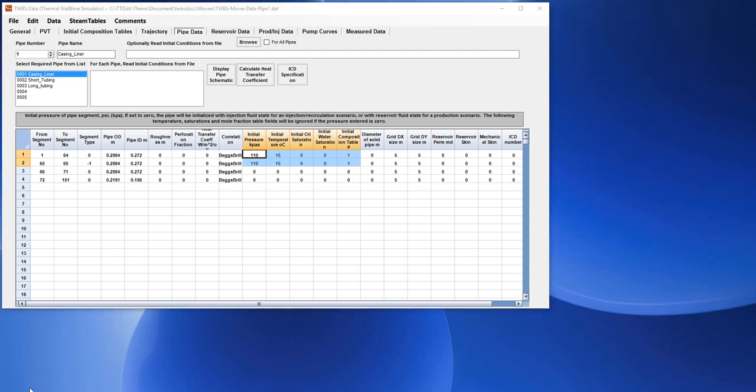The diameter of solid pipe. This is used to account for instrumentation tubing or similar no-flow tubes that occupy flow area in the current pipe. Effective flow area is reduced by the diameter of solid pipe.